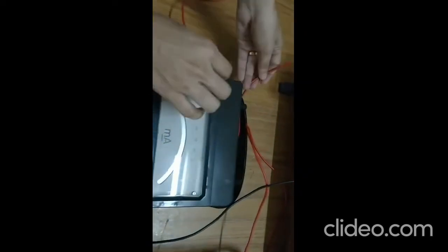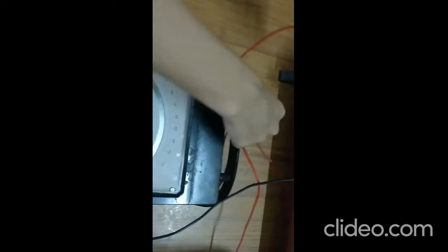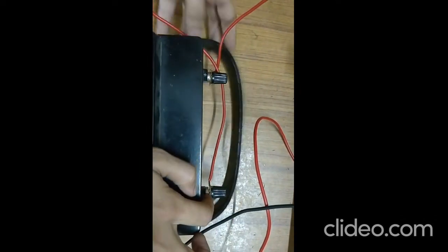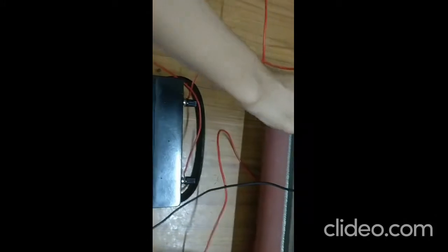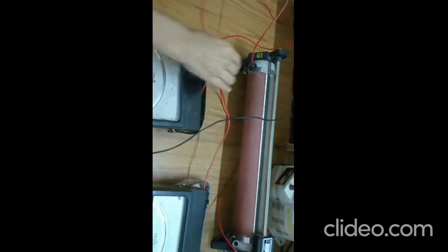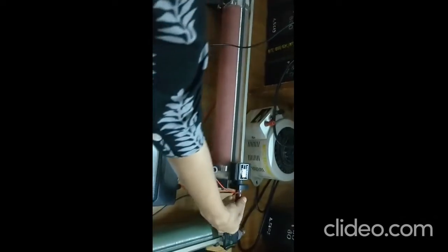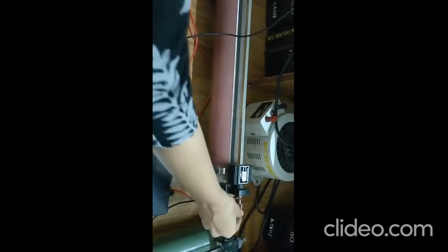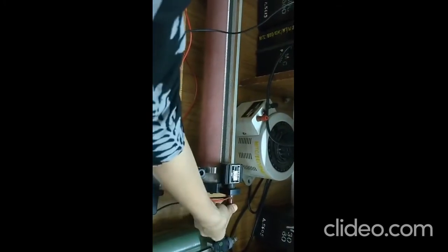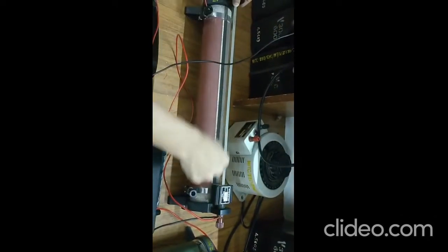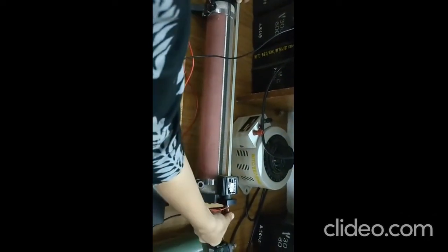In the supply, first we have an ammeter. As I have told you, the positive will be connected to the positive probe of this ammeter, and the negative to the negative, and this negative is given to the rheostat. We are using this rheostat in fixed mode only. You can see that we have connected it on the variable portion, and here we have the provision of varying, but we are giving the entire resistance over here, even though it is connected in the variable part.